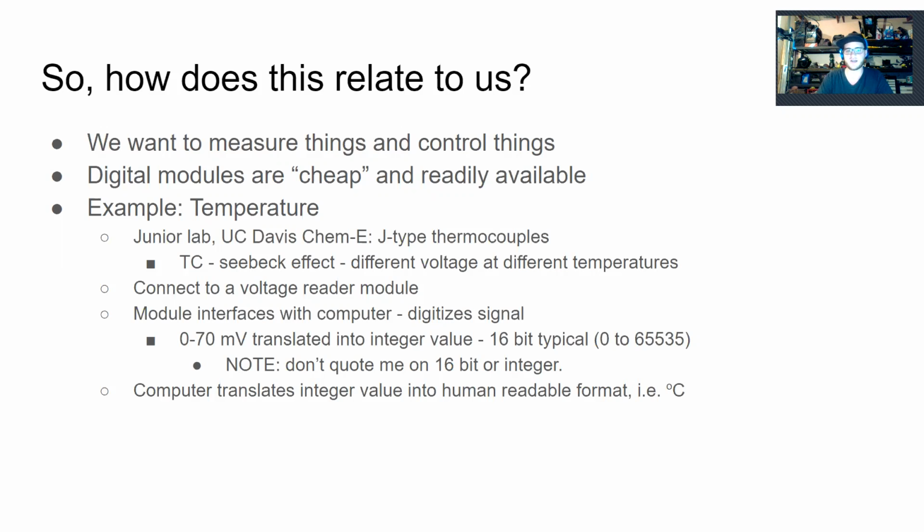But when you're doing really, really sensitive laboratory experiments, this starts to get really important. And so it's important to know not only how accurate is the calibration of your instrumentation, but how accurate is that digitization of your measured value. And so you explore that actually hopefully in pretty good detail when you do that lab.